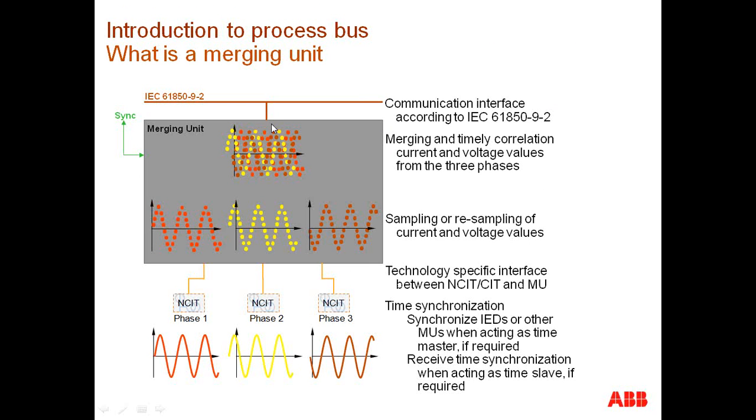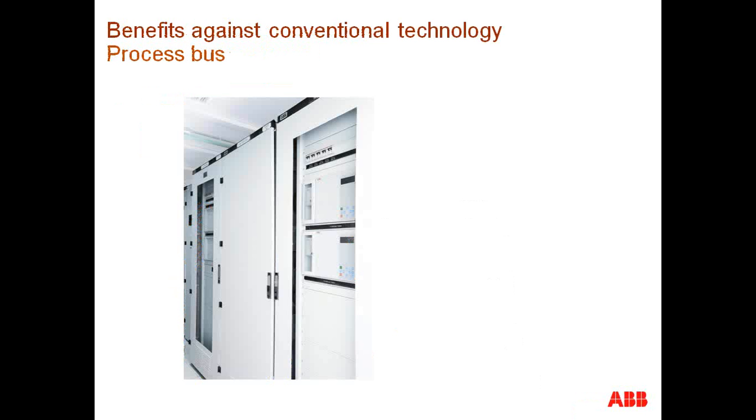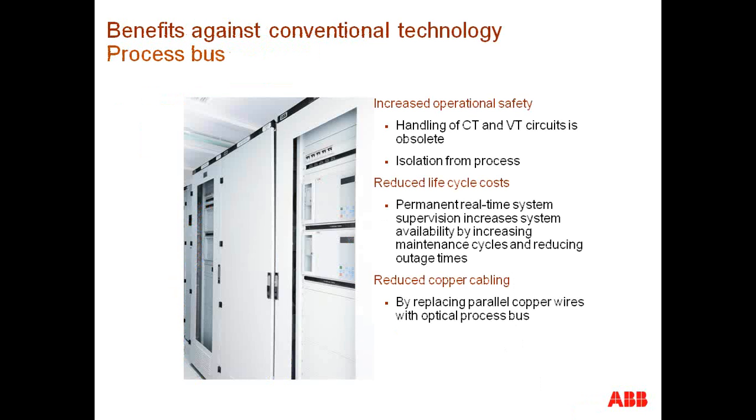And this slide just refers to the synchronization. It is important that each relay or each IED that's going to be subscribed to these data streams have the capability of aligning these signals. And the way those signals are aligned is based on a definite time reference, which, as defined by the 61850-9-2LE implementation guidelines, is based on PPS, pulse per second.